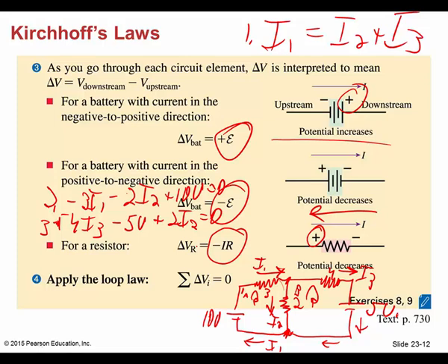And so now I've got 3 equations and 3 unknowns. I've got 3 currents, 1, 2, 3, and you can't have any more equations than unknowns. So then I could start solving my simultaneous equations. What would I do first? Notice I've got an I1 and I2 here, and an I3 and an I2 there. You add both of these equations together, and notice how the I2s cancel each other out beautifully. Then you have to do a substitution, getting all equations the same. So I would substitute I3: I3 is equal to I1 minus I2.